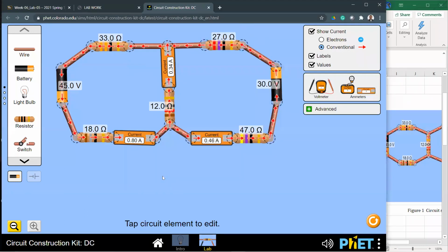0.34. Okay, now if we're doing this in an in-person setting, we don't have that much freedom to connect three ammeters. We have only one ammeter per group. So what we're going to do is break one connector at a time, measure it, reconnect it, go to the other place, and then break it, connect the ammeter, measure the current, and then go on like that. Okay, but this is fine. It's a simulator. We'll add as many ammeters as we wish. Any question?